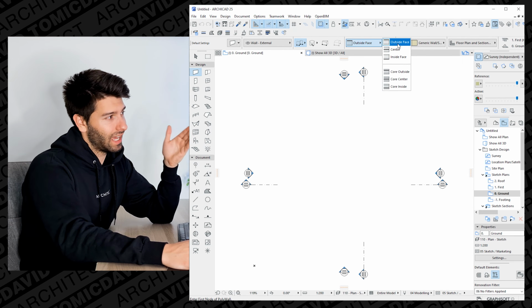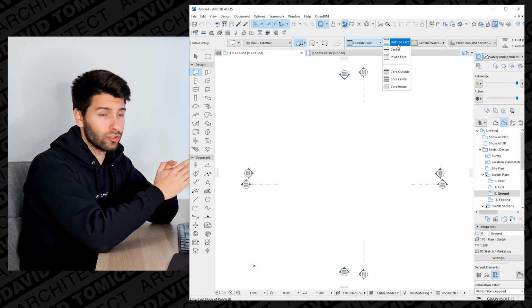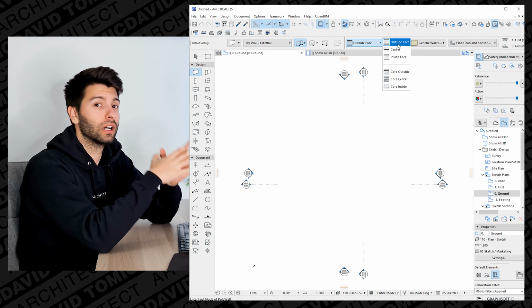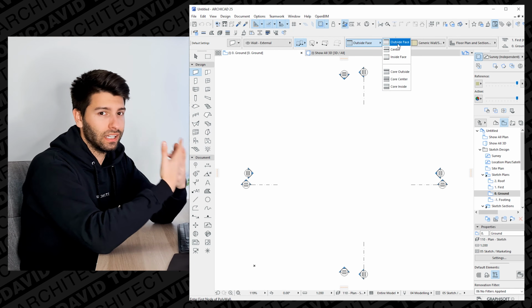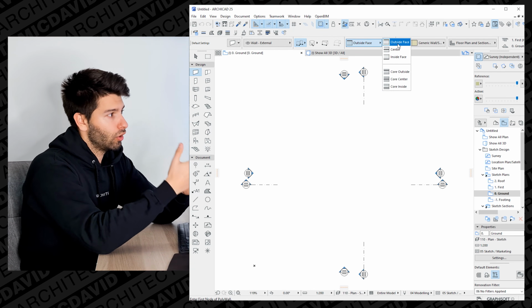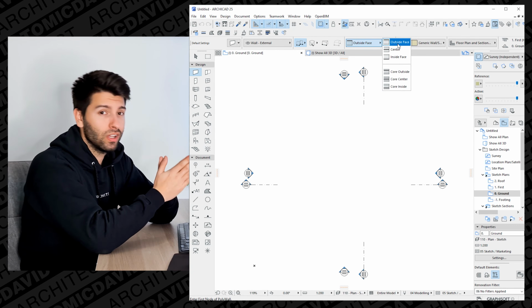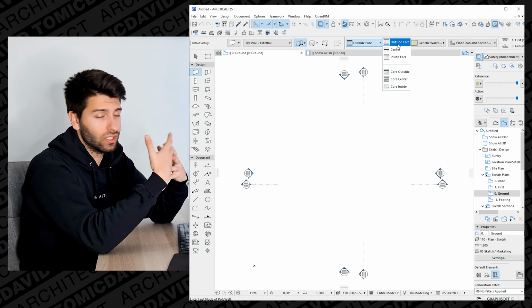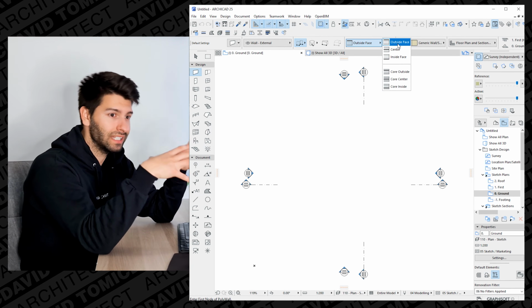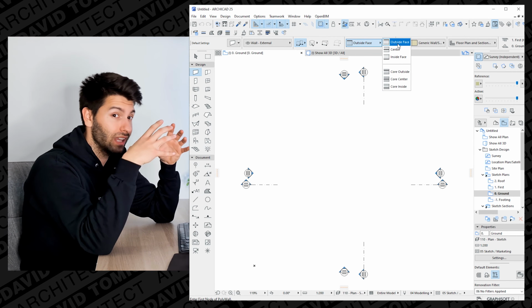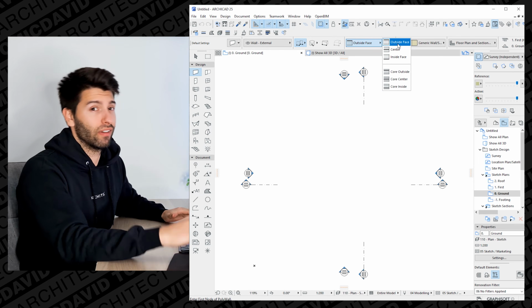But the reason I have it as outside face, drawing with the outside face, is because once it's submitted to council, the council has approved it. It can no longer move outside its parameters in a residential property without affecting another council requirement. So if, for example, a wall structure changes and it goes from a 90mm timber frame to a 120mm timber frame by the choice of either myself, the client, or anything else, it pushes the whole house inwards, and yes, you lose internal space, but the actual physical house doesn't move. So that's why I always keep it as outside face personally.